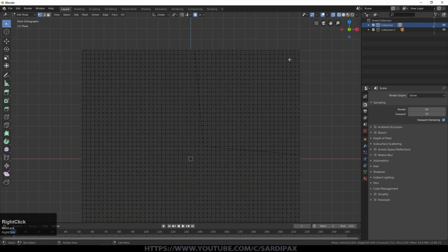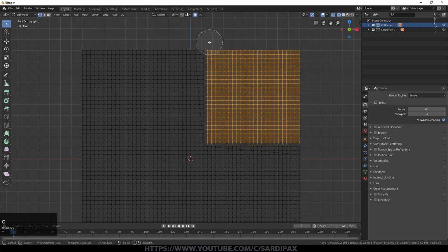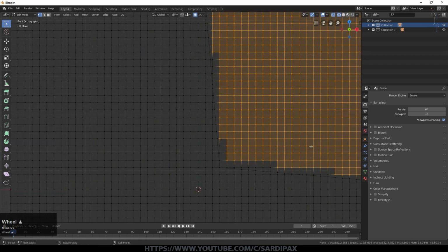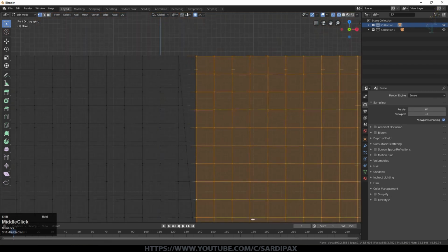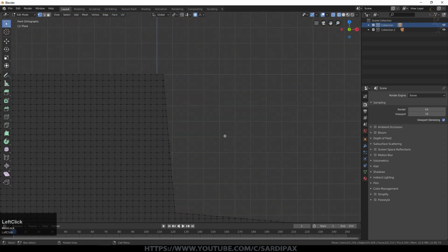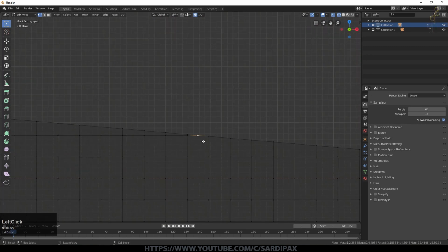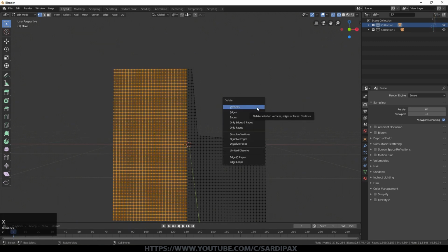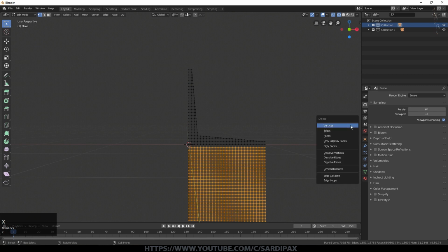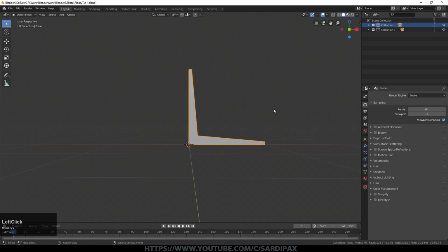So I'm now going to box select most of those, and then use C just to select the rest of them. So I'm selecting the vertices I'm not going to need. And we'll zoom in and just select, holding Shift down now just to select the remaining ones. Exactly what I'm doing will become clear in a moment. And then press X or delete and say vertices. Where we've got a funny one like that, just select it and make sure it moves around on its own, which it does. And now I'm going to box select. So there's the center. I'm just coming back from the center like that and delete all of those, and box select again and delete those. So if we go into solid view now, we've just got this very basic shape.